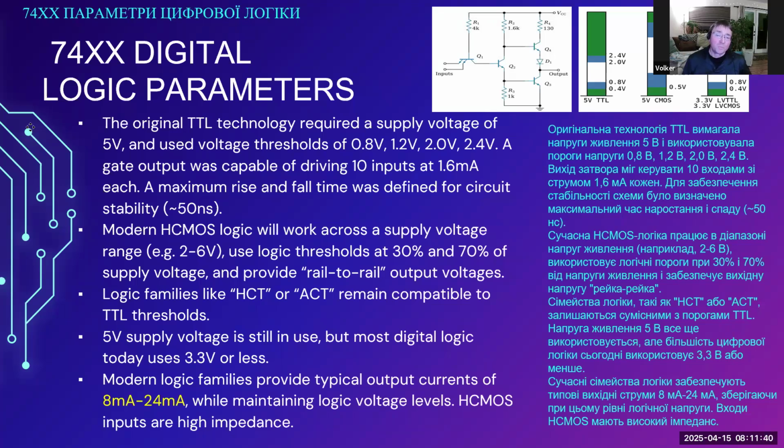It would be very unusual for a microcontroller to supply more than 25 milliamps. And in any case, if you're using a microcontroller, you should not be maximizing the output current out of a pin, because it might affect other peripherals on that microcontroller, in particular the analog to digital converter.